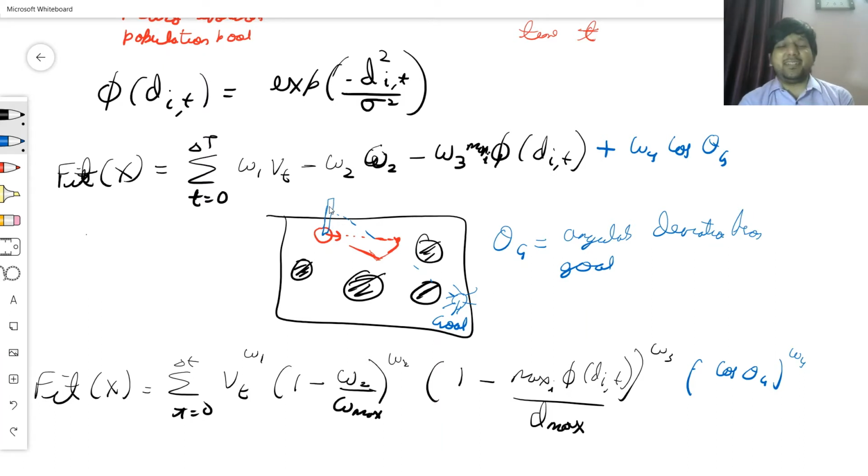We've used it in swarm robotics plus potential field to calculate the attractive potential. That's exactly how we calculated the attractive potential, by saying that I've got sensors which measure the relative direction to the goal. So an omnidirectional light sensor will sense light, an array of microphones can sense sound, and so on and so forth. So we've already seen how to calculate theta g when doing swarm robotics with a potential field. It's the same term over here, and I just plug that in here.